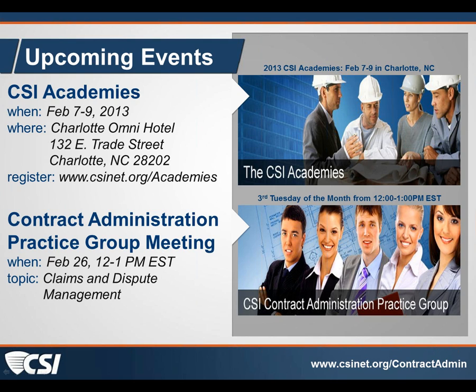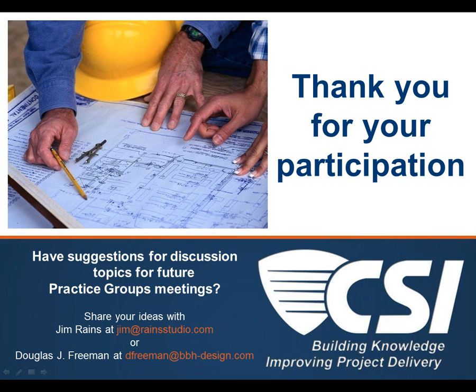Mitch Miller has a question: how many times do we review a submittal, incomplete or inaccurate submittals? Good question. I've seen this done before, you may put in your specifications that you're going to review submittals twice, and you also may have it in your agreement with the owner. Anything after that is above and beyond or additional services. So if you get something once and you reject it because it's incomplete, and then it comes back again and it doesn't comply with the documents, you send it back the second time. If you've got it in your documents the third time through, you can request additional services for it.